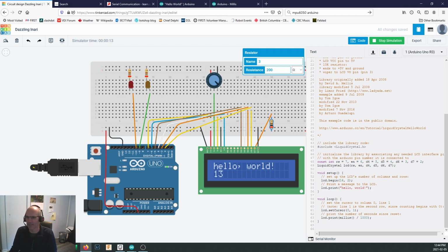I come in here and I say, well, these are going to be the pins that I'm using because I'm hooked up to 7654321 on the Arduino. Okay, my setup routine right in here. So this is all done before I get to setup. I call this our definitions and declarations, where you tell the computer a little bit about what you're going to be doing. If you think about your program as giving a speech, this would be like the person who introduces you. This is your opening statements, and this is the part of the lecture that you just keep repeating over and over and over again till everyone falls asleep.